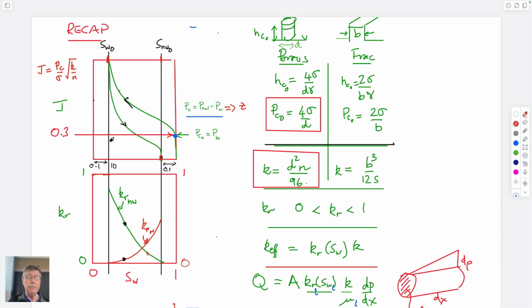I think it was to use this capillary pressure curve to scale pressures with saturation, so we could use them with elevation above the water table and with depth below the water table for NAPLs and for air and NAPLs alike. We noted the hysteresis, we noticed an entry pressure, a bubbling pressure. We noted that this was equal to 0.3 in terms of this Leverett function, which is non-dimensional, where we typically can easily get permeability by measuring it, can easily get porosity, can easily get interfacial tension, but can't very easily get bubbling pressures. So this is an easy workaround to be able to do that.